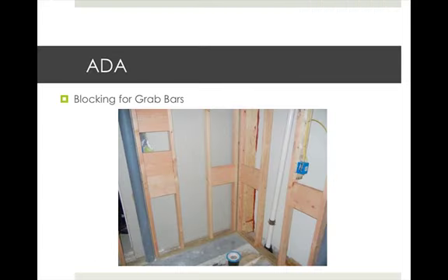Now, there are many aspects of bathroom design that are controlled by ADA, the Americans with Disabilities Act. The ADA does not apply to private residences, but many designers do consider these guidelines for the future needs of their clients. Many apartment communities will design units for easy modification, like, as you can see in this photo, placing extra blocking, these boards here, inside the walls so that grab bars can be installed down the road.